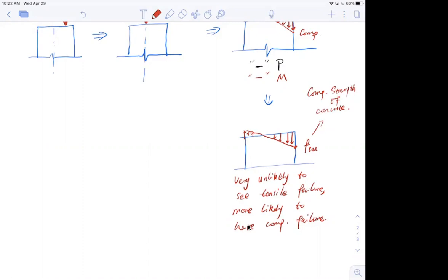Right? So that is to say, if we follow the mechanics of materials, P over A, which is the compressive stress, plus the bending caused compressive stress, My over I, when that equals FCU, it fails.